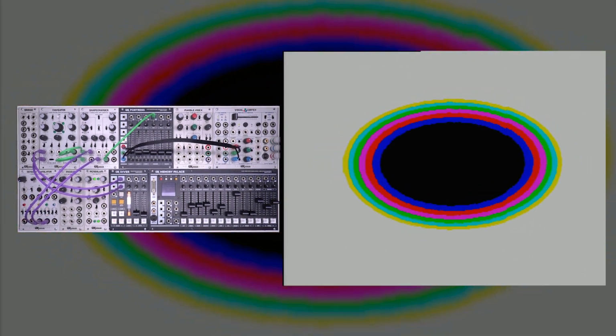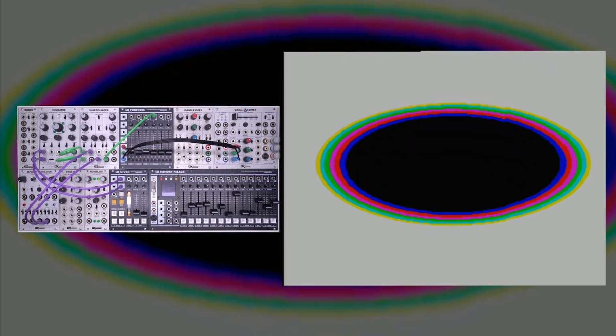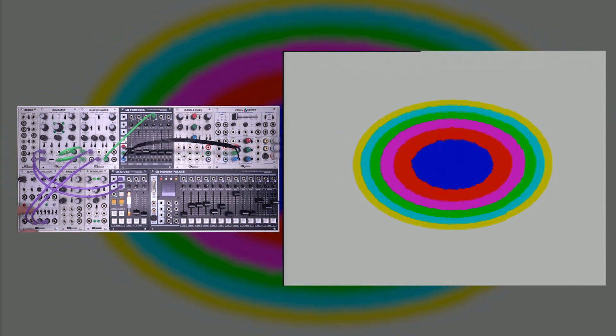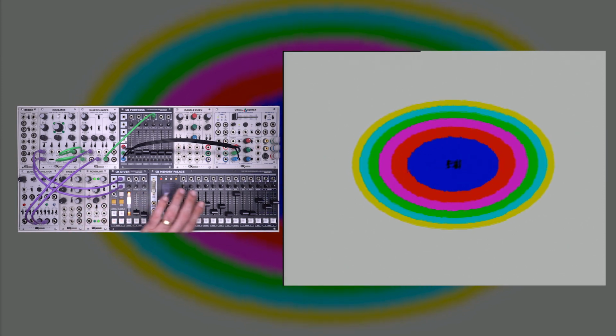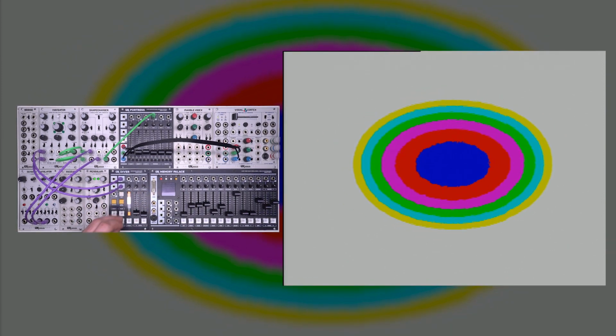And of course, fast is going to give you the fastest and most erratic results. There's also a switch on each channel between AMP and IMP. AMP stands for amplitude envelope. IMP stands for impulse envelope. The amplitude envelope is going to give you a more smooth envelope on the output, whereas the impulse envelope is going to give you more of a spike.